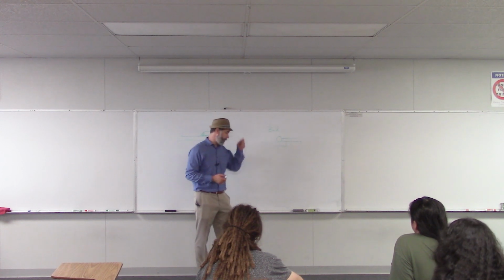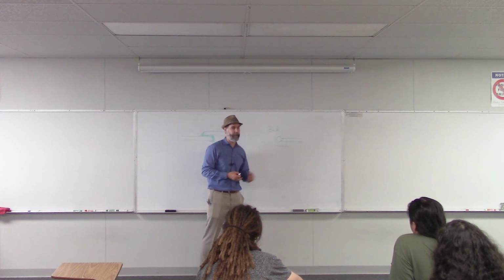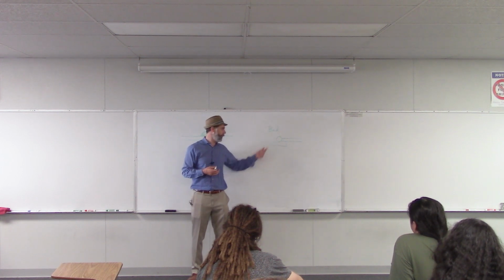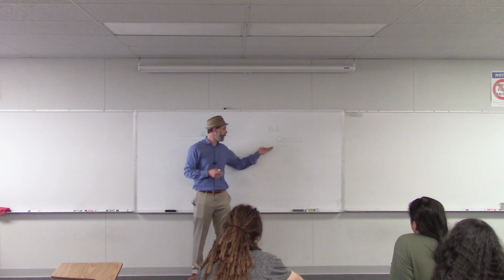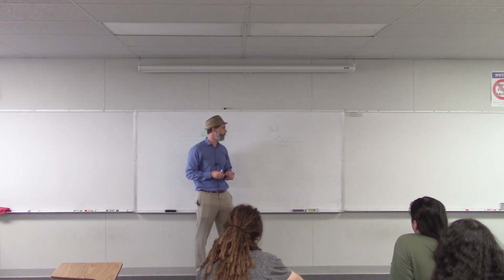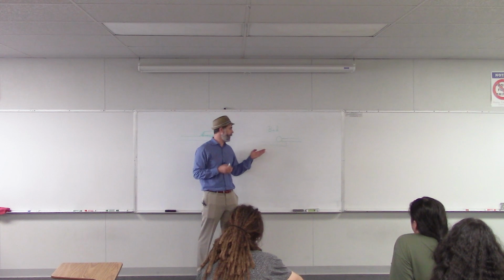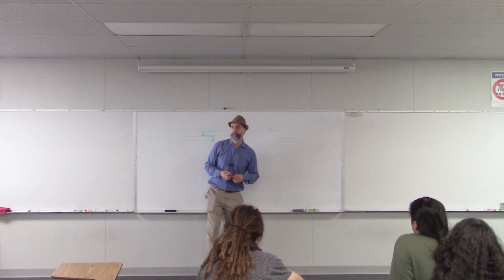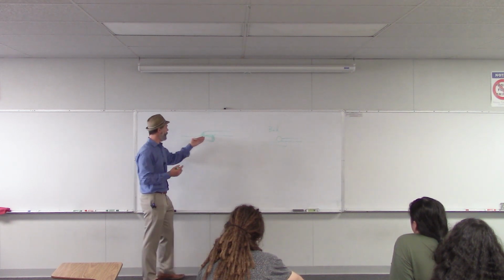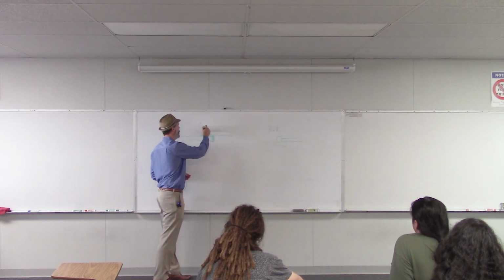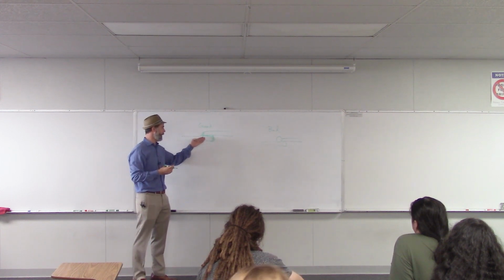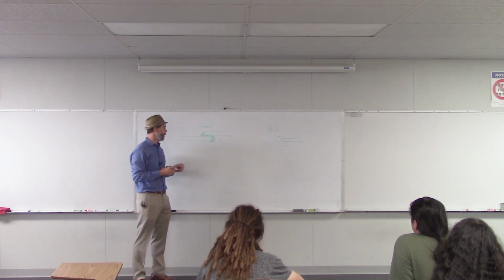And that's bad for a couple of reasons. First of all, that little tiny connection point doesn't make a good electrical connection. So there can be a lot of resistance. Also, that little tiny point doesn't make a strong mechanical connection. So it can easily snap off and fall away. So what you want is something like this, where the solder flows over and really flows all around and makes a good strong connection to your components.